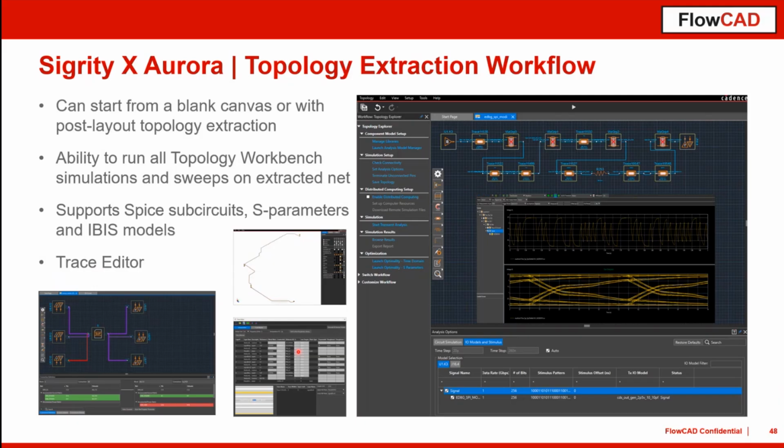And this transmission line editor is also a very powerful tool because you can use the layer stack-up structure and all those stack-up parameters of your PCB, that means laminate, dielectric losses, dielectric constant, edge factor, copper roughness, and all these parameters go into the calculation of your so-called W transmission line model. So this can also be very helpful to do such analysis at a very early layout stage.